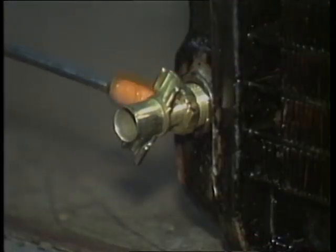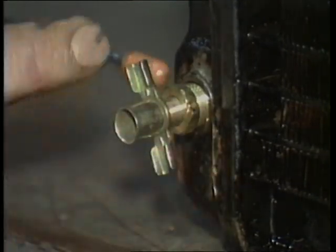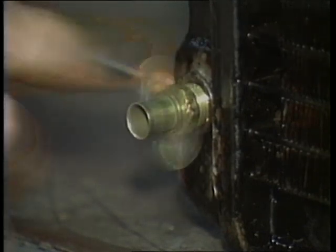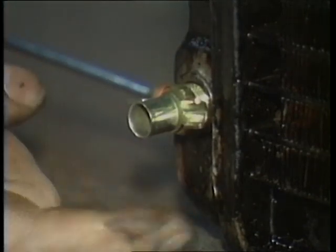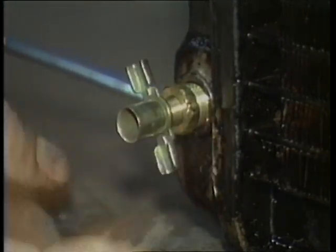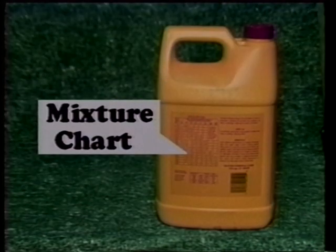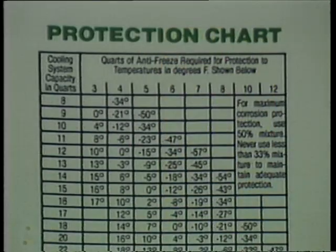To drain the coolant, open the petcock on the bottom of the radiator. Then add the correct mixture of antifreeze to water to restore the cooling system solution. A mixture chart on the back of the antifreeze container often gives information on how much antifreeze should be used depending on the capacity of the car's cooling system. Compare cooling system capacity on the left with the coldest possible temperature to find the number of quarts to add to the system.